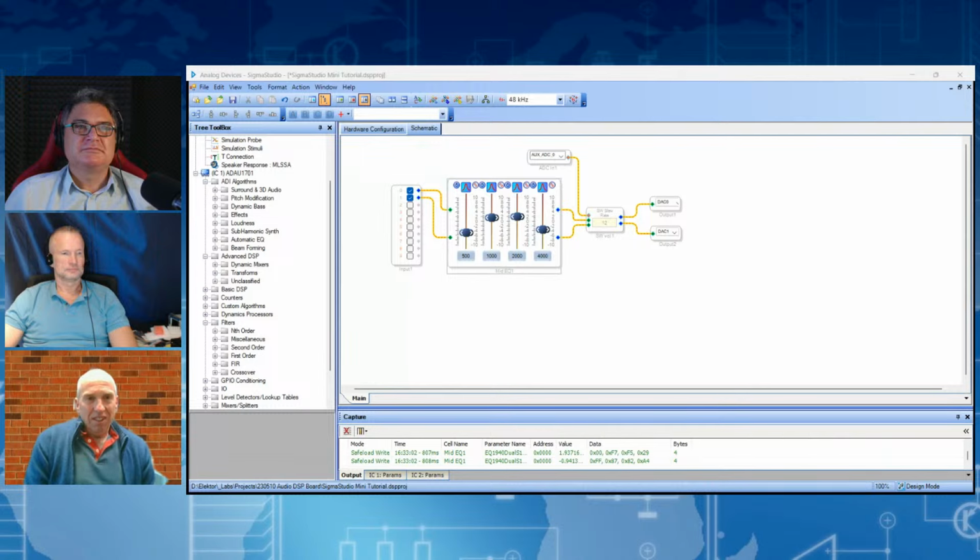It was designed to connect all sorts of equipment from any manufacturer in a safe way. So that's why they put in an optocoupler. Well, I better get some optocouplers in stock here so that I stop trusting and hoping for 5 volt tolerance. Now, yeah, well, I published a MIDI interface some years ago, a small module compatible with 5 volt and 3.3 volt drivers, and with different connector options. With any luck, I can find that now.